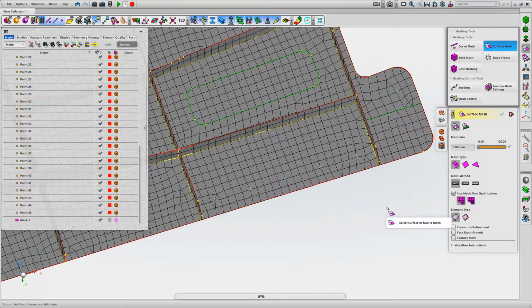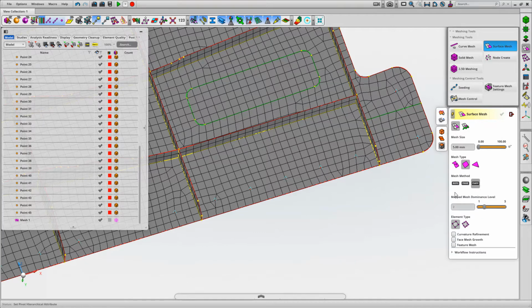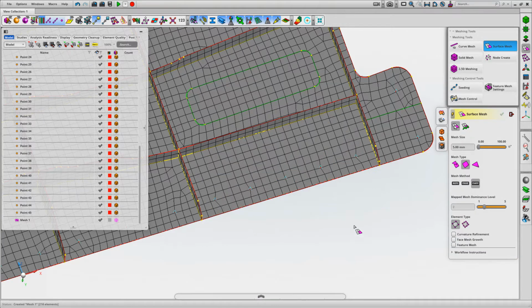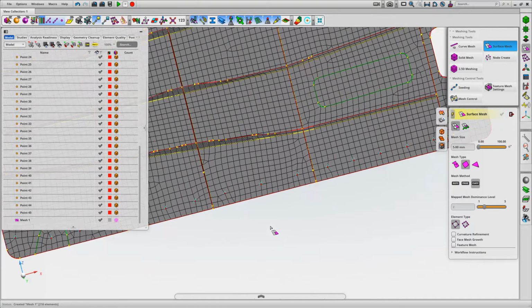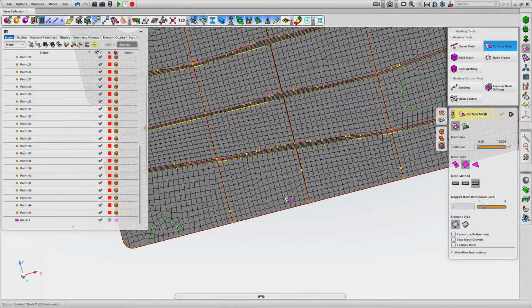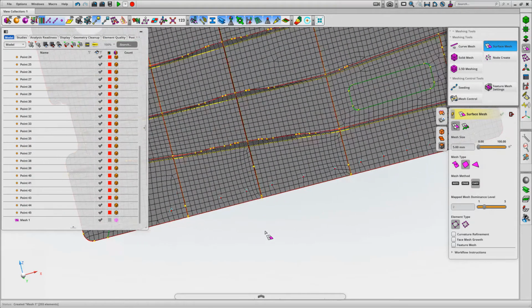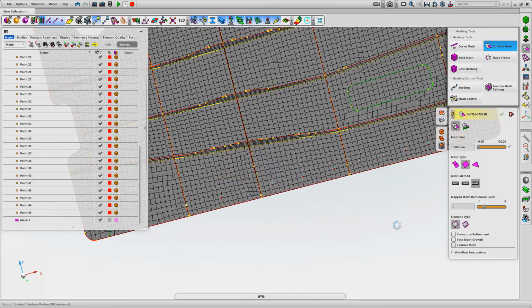So what I would tend to do is mesh the whole structure with a mixed mesh using the auto algorithm. But for these detail regions, I'd probably switch to quad only with a mapped algorithm, okay? So just select that and it updates, and we've got a much better mesh definition. We've hit all the fastener nodes. So really just a case of working our way around and getting those, actually we'll do those all together and then we'll get better definition.